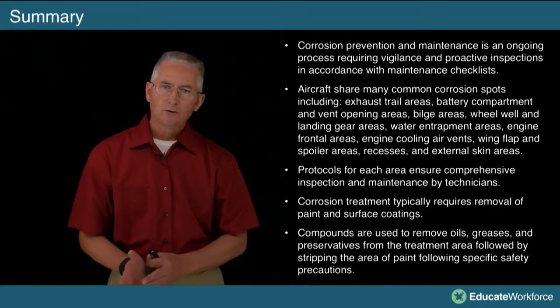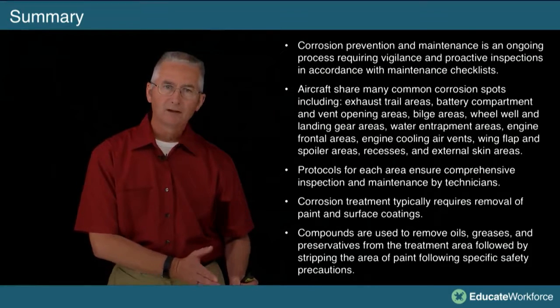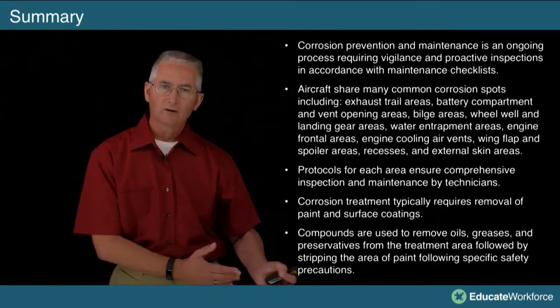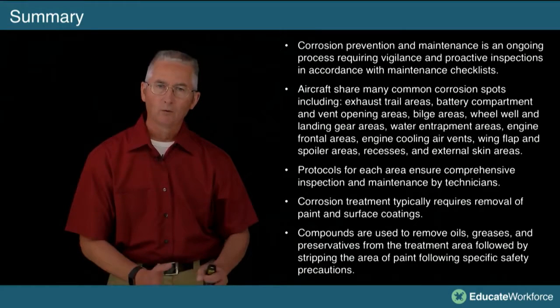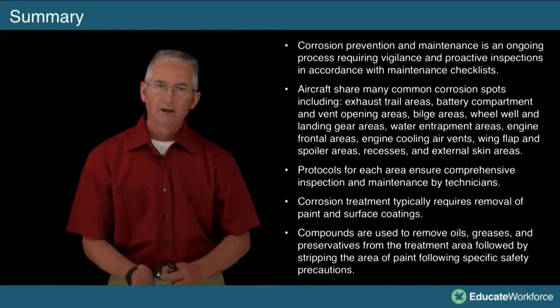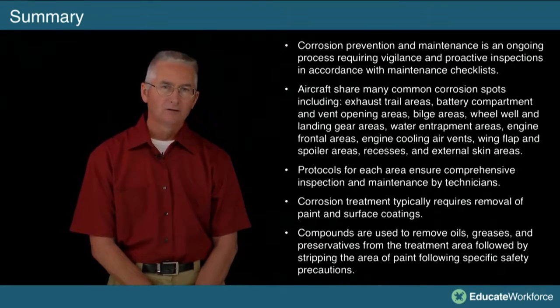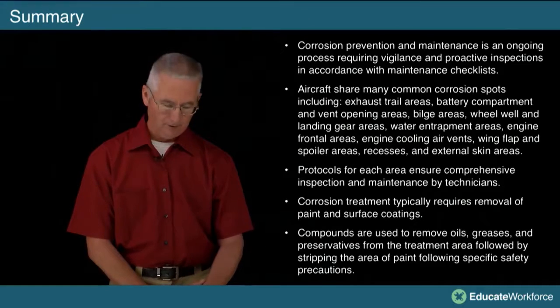Make sure you're using your emulsion cleaners to remove the grease and the oil. Keep your airplane clean so that oil and grease aren't holding moisture up against the airplane or holding dirt against the airplane. If you keep your area clean and presentable and the paint intact, you're going to reduce the chance of corrosion. You're going to save yourself money and time in the long run.